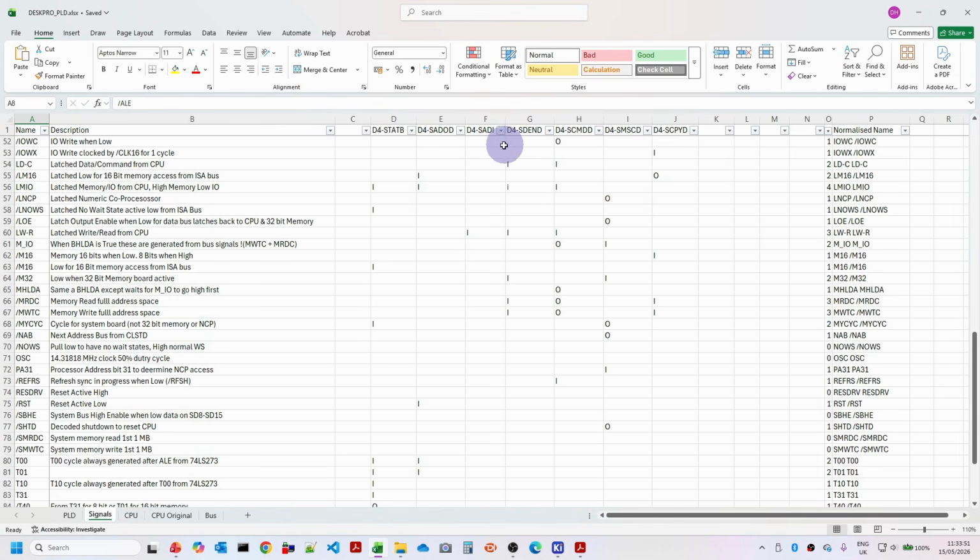and this diagram here just indicates the interdependencies between all these things. So you'll see that in some cases there won't be any outputs on these lines, so the outputs may come from a processor or from the ISA bus. With a lot of the chips though, one of them will be handling the outputs and all the others will be making use of the inputs. Now, one of the things I was thinking here is that these sort of 7 or so chips which are used for doing all of the bus control logic are candidates for replacing with a complex PLD.